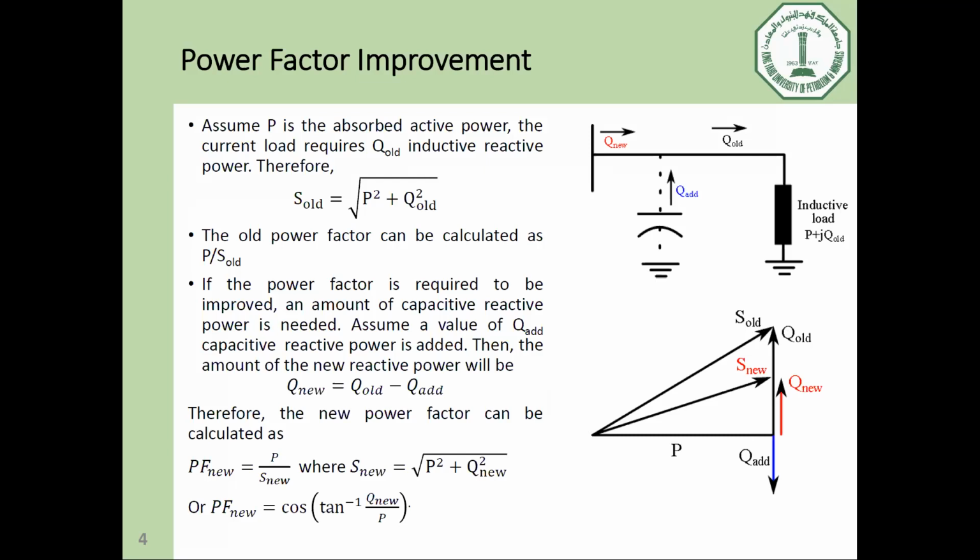And this cost is overhead on the electricity company, not the user itself. Because in our homes, we have electricity meters called kilowatt hour meters. So we only pay the cost of P, not the cost of S. Is it clear?